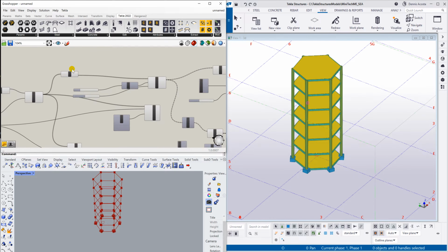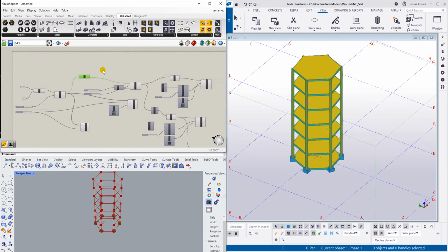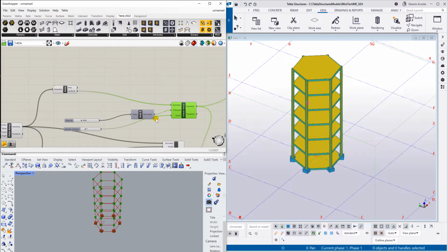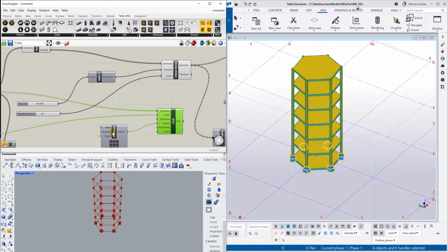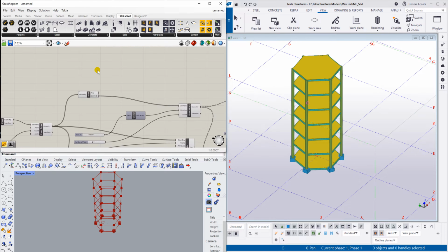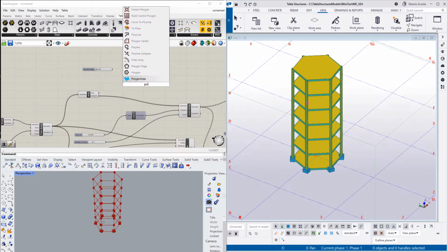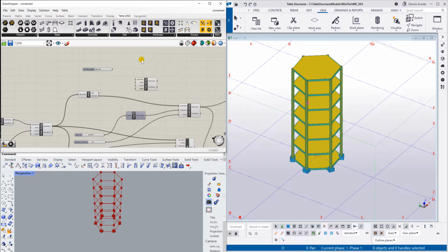So let's do that first under the area here. Where's the area? So here, this is the area. So we need to do that under this area. Just move this one a little bit because we're going to use this one here. There you go. So just double click to get the radian value. You simply type 0 and then angle, then 2 times pi. Enter. And then double click again. You type here again polar array.